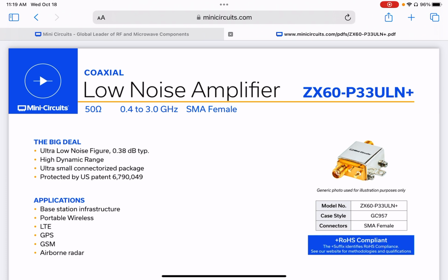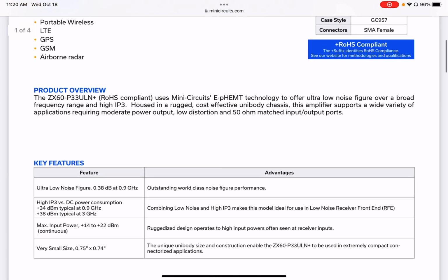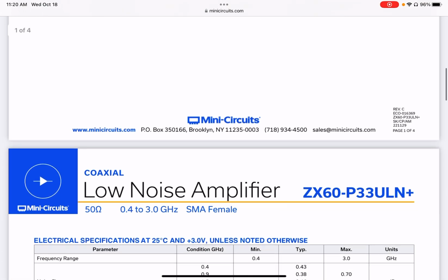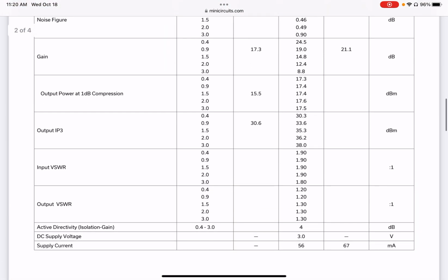It says 50 ohm up here on the top left. You probably can't see; I can't point to it, there's no way for me to highlight it, but it's up on the top left. It says 50 ohm. So that means they've tried to make a 50 ohm input termination and 50 ohm output termination for the amplifier. So if you have a 50 ohm characteristic impedance transmission line going to this amplifier, it should be perfectly well terminated. As you can imagine, the real world isn't perfect.